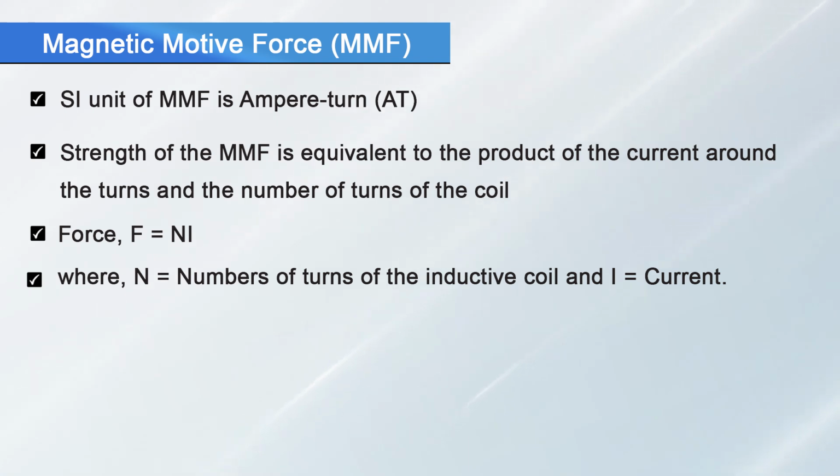The steep part of the curve where flux increases rapidly is called the unsaturated region, meaning the core is unsaturated. This transition between the two regions is sometimes referred to as the knee of the curve. It is to be noted, and is very important, that the flux produced in the core is linearly related to the applied magnetomotive force in the unsaturated region only, and thereafter it approaches a constant value regardless of MMF in